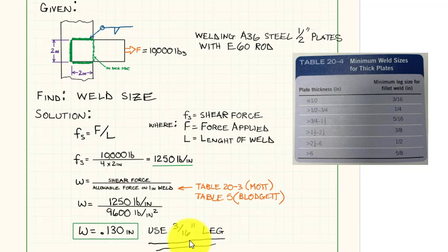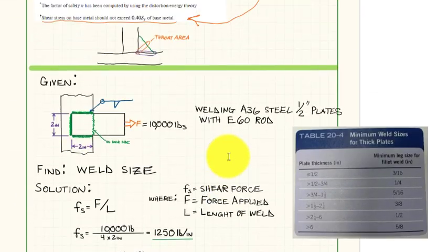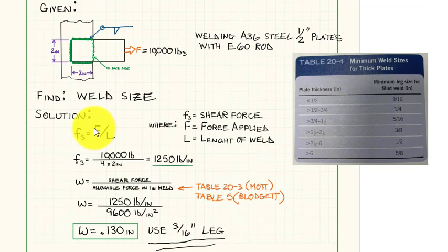But again, we would want to think safety factor and not design things at a safety factor of one. So you kind of saw 2 different approaches of the same problem, finding the shear stresses inside here, and then also coming in here and looking at the weld size for the same type of application. So between these two, you should be prepared for lab.